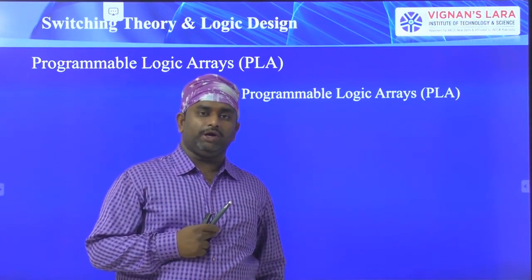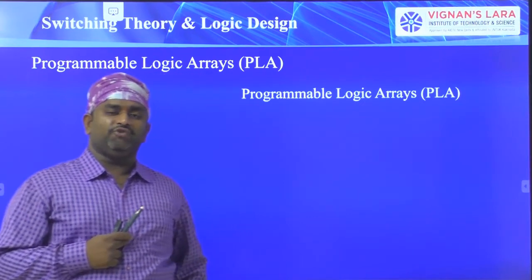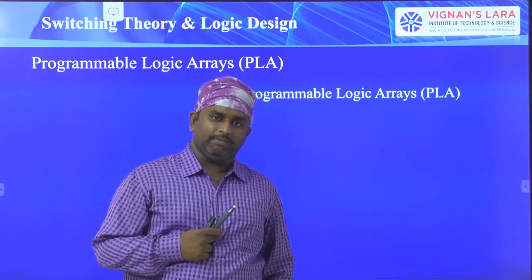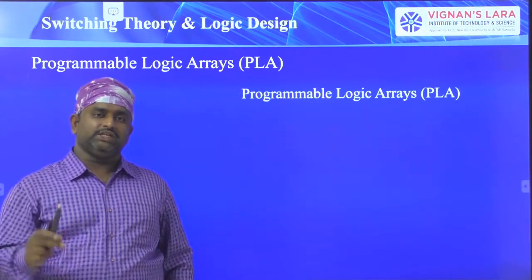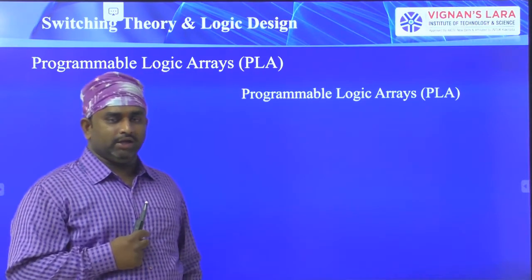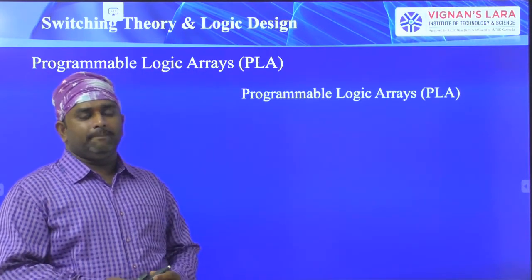In the programmable read-only memory we have the freedom of connecting the OR gate inputs based on our requirement, but the AND gates have fixed input connections, which we have taken in the form of a decoder. So that is about PROM and PAL.